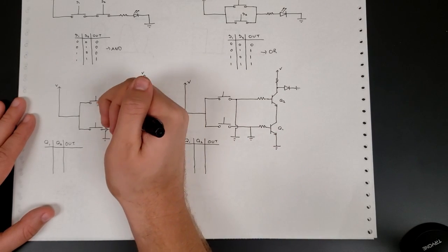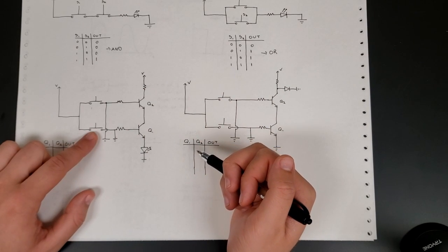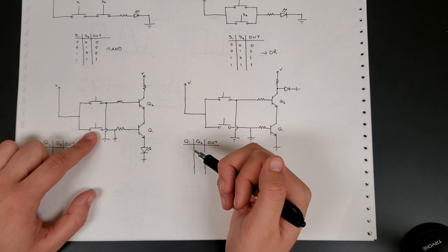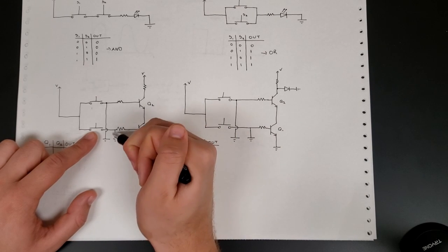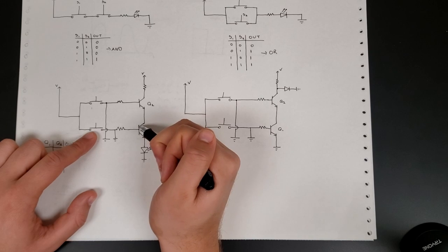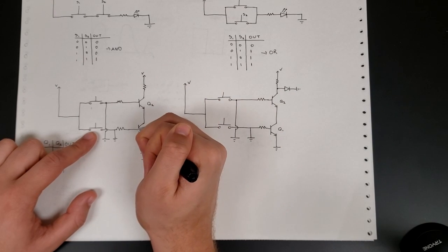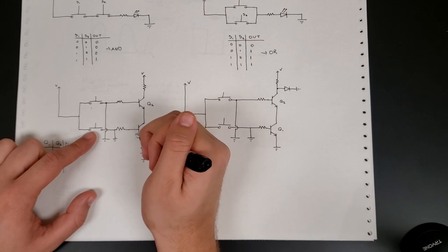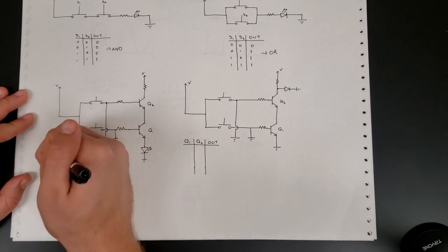We can see we have two switches over here, one for transistor Q1 and one for Q2. If the switch is open for Q1, that means my base is going to be grounded because I have a ground here, which means my base-emitter voltage is going to be 0, which means this transistor is in the cutoff region, or it's off, which means I cannot have any current running through it. So unless I have some voltage at the base, these transistors just act like an open switch. Keeping that in mind, let's now do the truth table here.